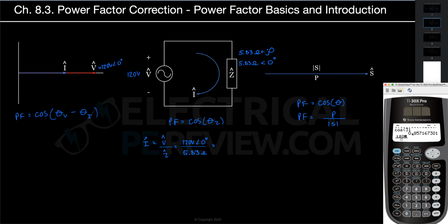I'm going to show the angle, but anytime you have an angle of 0 degrees, you can just leave it out and the math works out exactly the same. All right, that gives us a complex current of 20.6 amps, just like before, except now we have an angle of 0.